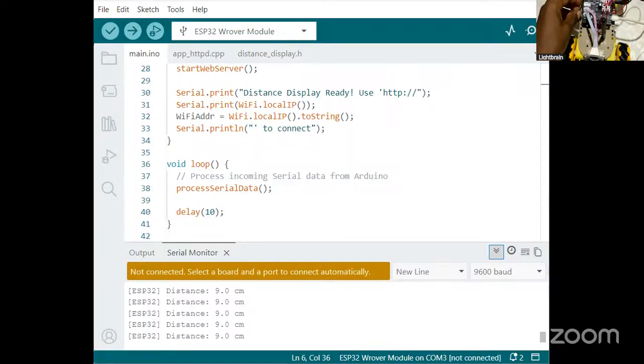And there'll be a sound on the computer. Now it will say, okay, the board is connected. But because this one here is the ESP32, the board still is not connected. Okay, it's not connected. And anytime you remove this one, the Wi-Fi will go off. It's like it's not connected, it's not powered, there's nothing happening. But remember, before you upload the third project, you still have to remove this. This one is the most important part to remember.